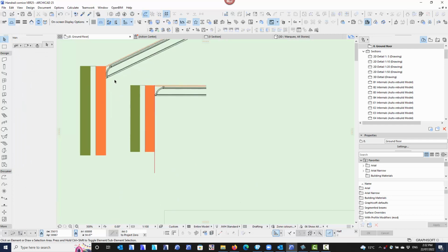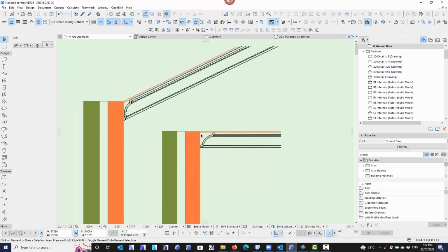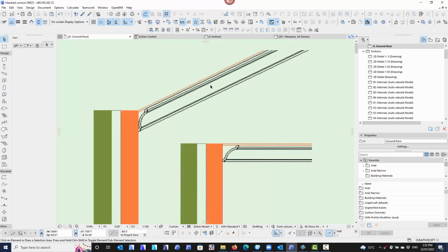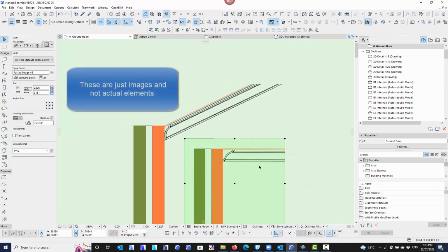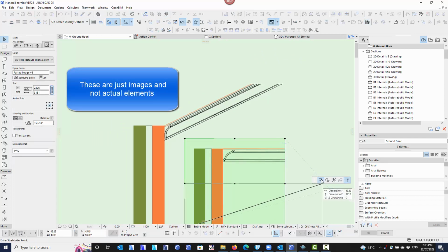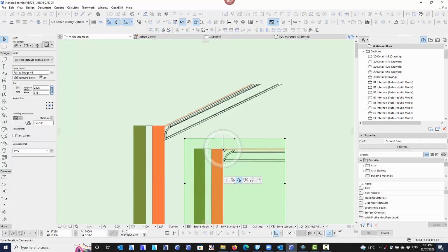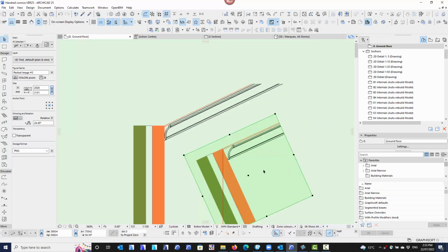Now, a raking ceiling, when you look at it, is basically the same as a standard flat ceiling, but you're literally just taking the whole thing and raking it. So we're raking the cornice up the gable wall, and we're also rolling this cornice in the side here. If you unrotated this, we've got a flat ceiling where all the cornices join. So it's as if you've taken this ceiling here and simply said, let's rotate from that point there and rotate it to our ceiling angle.